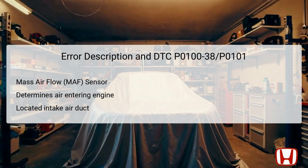If the sensor's output frequency deviates from the specified range, particularly on the lower end, the PCM will flag it as an anomaly and store the related DTC. This could indicate possible wear, damage, or a blockage in related air intake components.